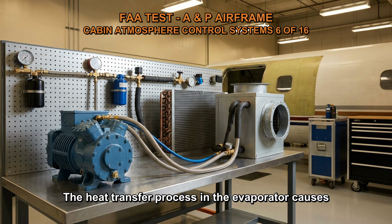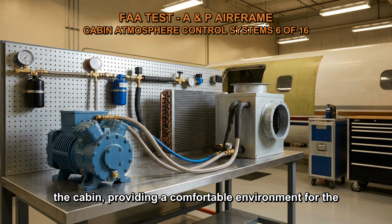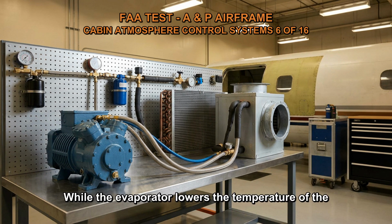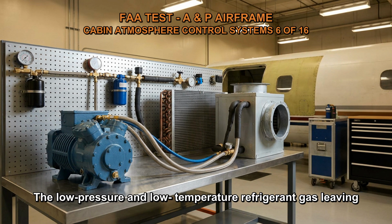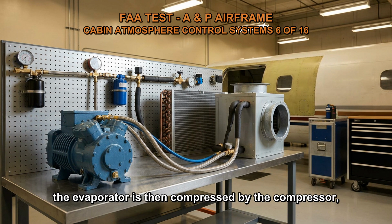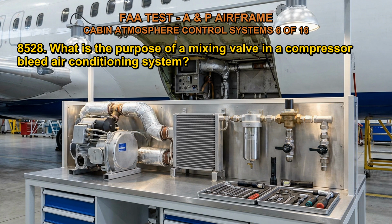The heat transfer process in the evaporator causes the cabin air to lose heat, resulting in a decrease in temperature. The cooled air is then circulated back into the cabin, providing a comfortable environment for the occupants. While the evaporator lowers the temperature of the cabin air, it also plays a crucial role in the overall refrigeration cycle. The low-pressure and low-temperature refrigerant gas leaving the evaporator is then compressed by the compressor, leading to the next stage of the cooling process.